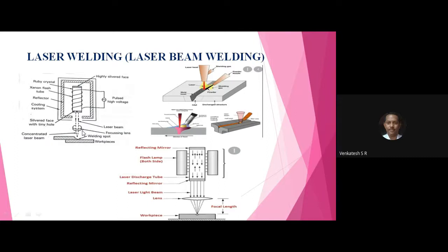So the principle of operation of this is the gun. From this you have the laser which impinges on the workpiece joint, or hits the joint and fills the gap with the electrode material or filler metal, and the laser has radiation which is maximum enough to melt the edges of the workpiece as well as the filler metal, so that you can fill the gap by using laser.